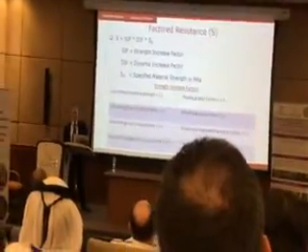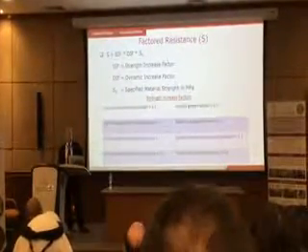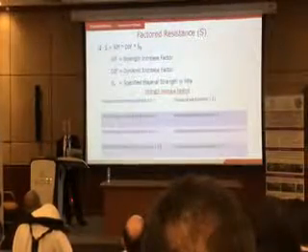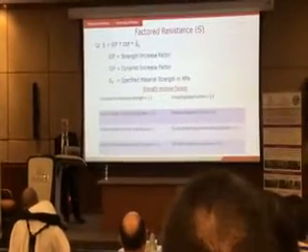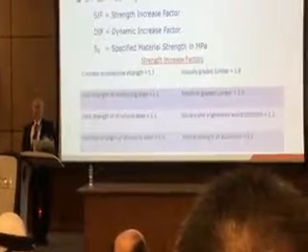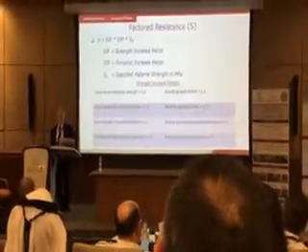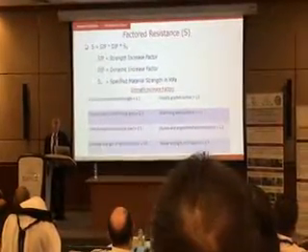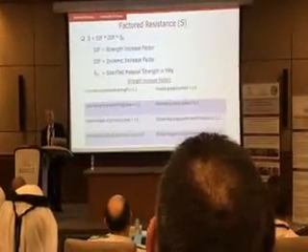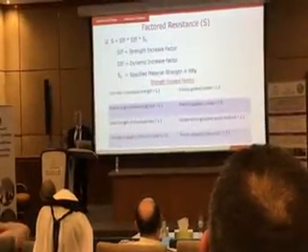And then there are two other factors that we multiply specified material strength. One of them is the strength increase factor. This is not that important. Strength increase factor is because we use safe values for material strengths. For example, in Canada, our design strength for reinforcing steel is 400 MPa, right? But in the lab, we constantly get 420, 460 MPa. In other words, specified strength is higher than design strength.